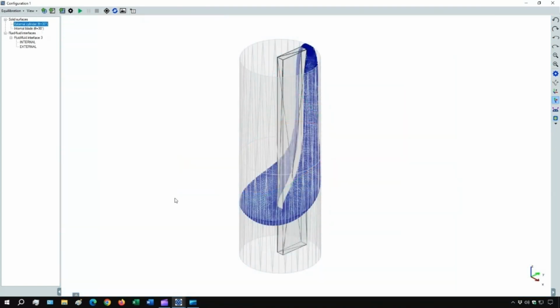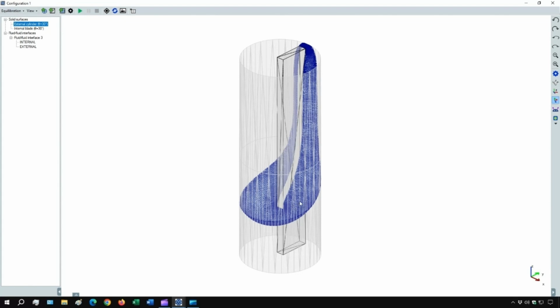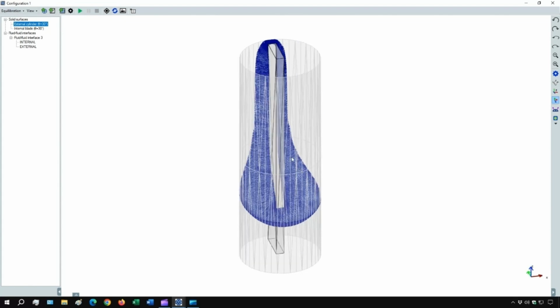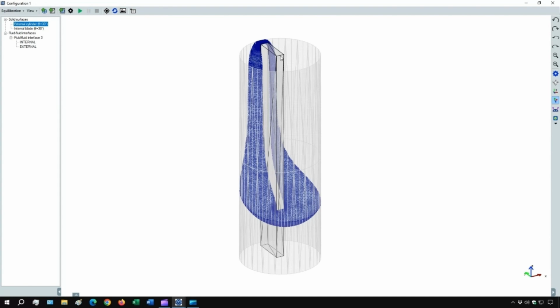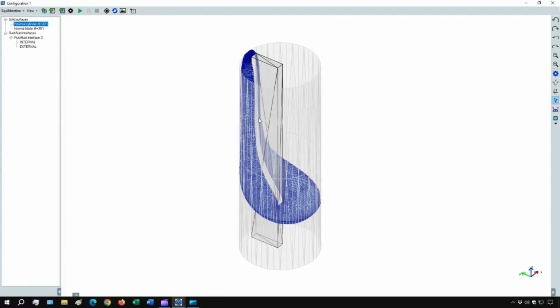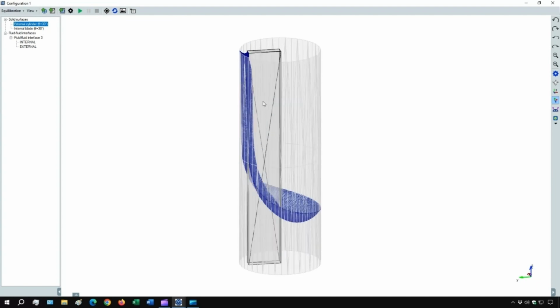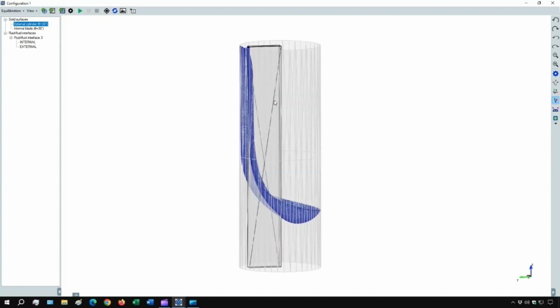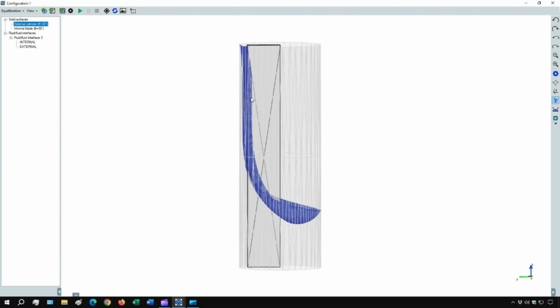This is the equilibrium shape of the fluid interface that we want to simulate. It represents the interface between two fluids in a cylindrical container with a rectangular blade located inside it. Gravity was not enabled during the simulation, so this could represent a propellant tank in microgravity, or a sub-centimeter cavity on Earth. Young's contact angle is 30 degrees, both on the cylindrical tank inner walls and on the blade walls. So, the fluid below has a strong wettability on these surfaces.